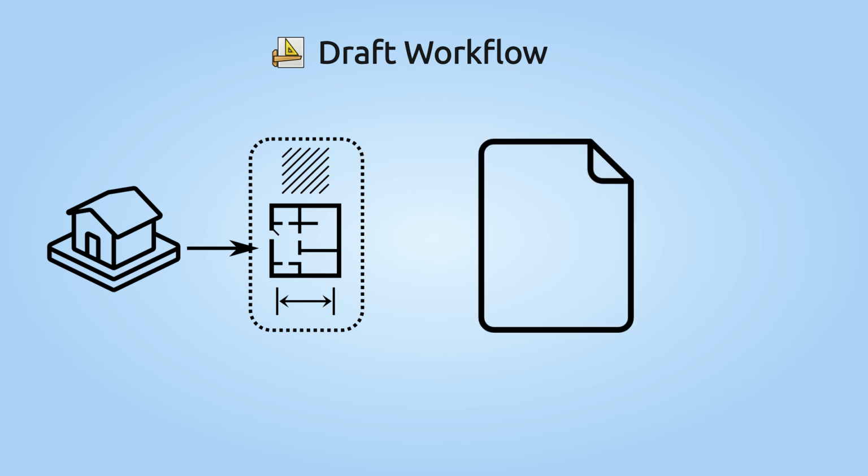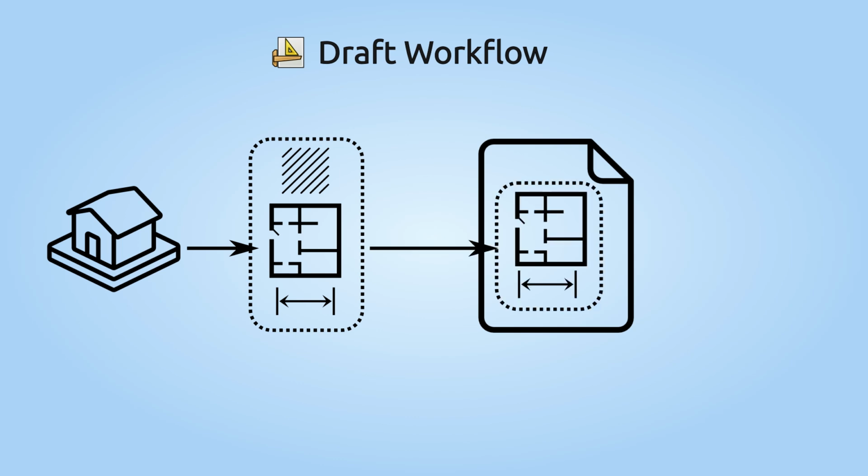Then, a sheet with a title block is created using the TechDraw workbench. The drawing containers can then be placed on the sheet. Multiple drawings can be placed on one sheet or on multiple sheets. The sheet is called a page in FreeCAD. Pages can easily be printed out or exported to PDF, achieving the desired task of creating construction documentation.